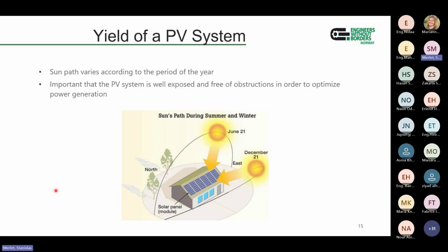So you will need to find an angle that allows okay wind loads, so that it is not acting like a sail in a boat, which is the angle would be low enough to avoid that, but high enough to allow for the rain to wash the modules a bit automatically when it rains.